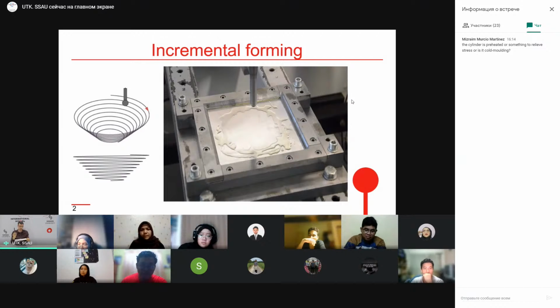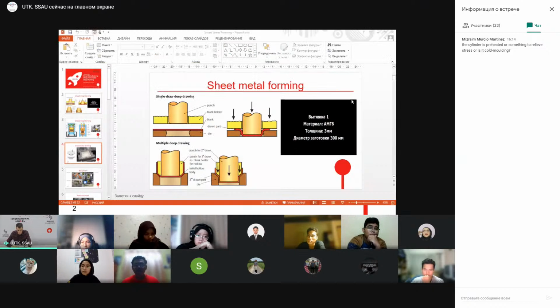And this tooling is universal. It's suitable for all parts and for all operations. And if our sheet is fixed, we can move the punch to the sheet and make a forming operation by movement of the punch step by step. For example, on the left, you can see the example. We create a force by a punch, deform the sheet, but locally, deformation is not very big. And then we move the punch in such a path that this path should coincide with the shape of the part. I'll show you the video, and I think that it will be clear.